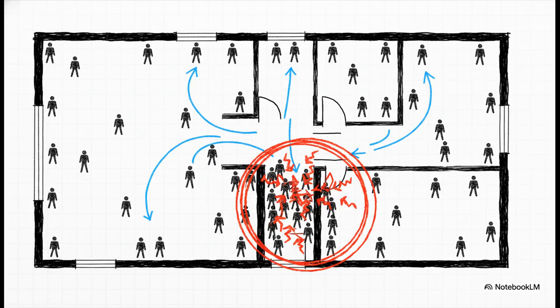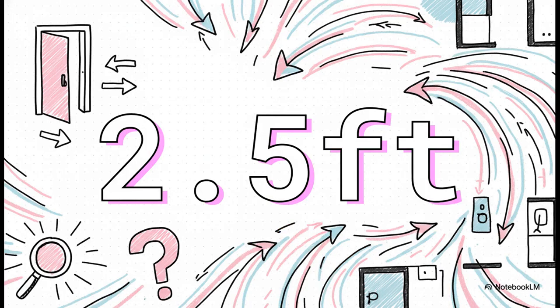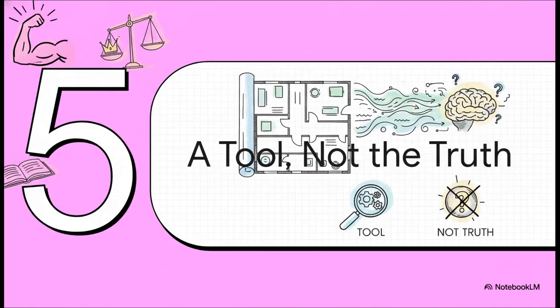And it's not just about physical properties. You can also simulate human behavior. You can max out the occupancy for every room to simulate a party and see where people get stuck. You can identify exactly which doorways are going to become total bottlenecks. To run that stress test, the simulation changes the standard 3-foot doorway parameter down to a narrower 2.5 feet. By changing just that one number, you can see how the circulation flow for the entire apartment changes, pinpointing a potential design flaw.